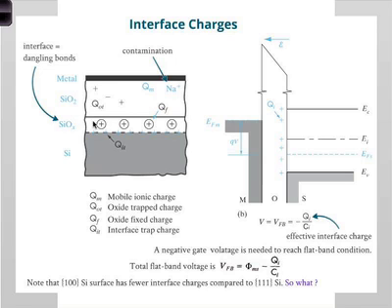And then at the interface between the oxide and the silicon, clearly you have to have something happening because you're going from silicon oxide to silicon. So you have some bonds which have to be rearranged and so on. So you expect some dangling bonds, essentially, some bonds which are not satisfied. Okay? Which of course means that you have electron charges. Essentially, you can have crystal imperfections, you can have charges that are trapped, electrons that are trapped, or holes that are trapped, and so on and so forth. So you get charges which are typically positive in this particular case because this is a p-type material, and QF, you have oxide fixed charge.